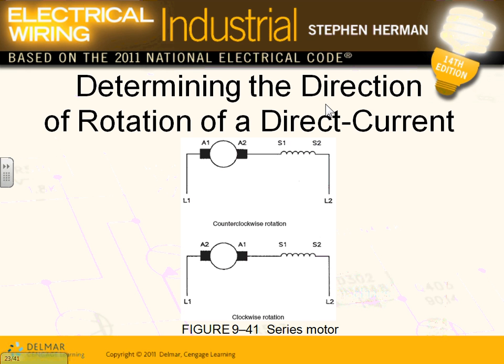How do you change the direction of rotation? Can you guys see how A1, A2 are connected here? This will get you counterclockwise if you put the A2 here and the A1 here. So you flip these. Can you guys see how they flip them? How do you flip them? You take the wire that's supposed to come here, grab it, put it here. And you take the wire that's supposed to go here, flip it, and tie it there. It's really not complicated. Flip the wires. And that will get you clockwise and counterclockwise rotation.